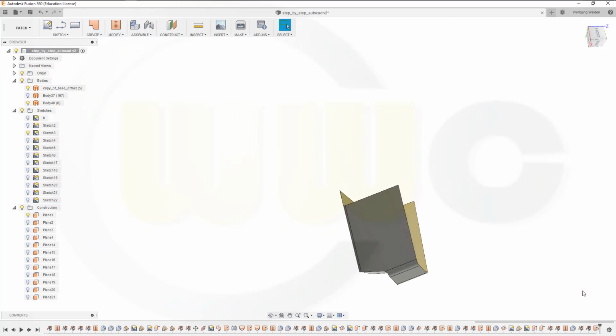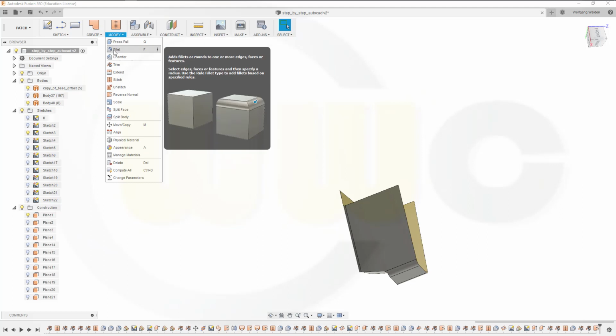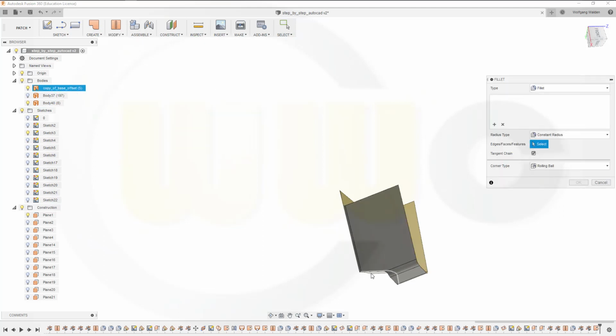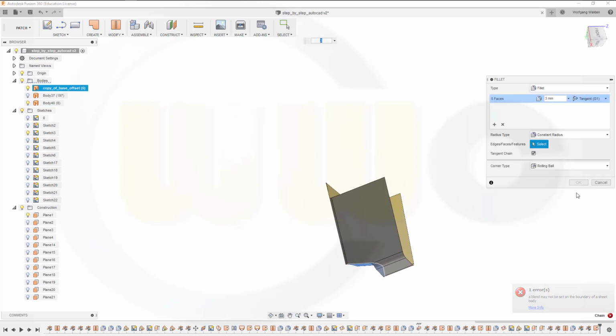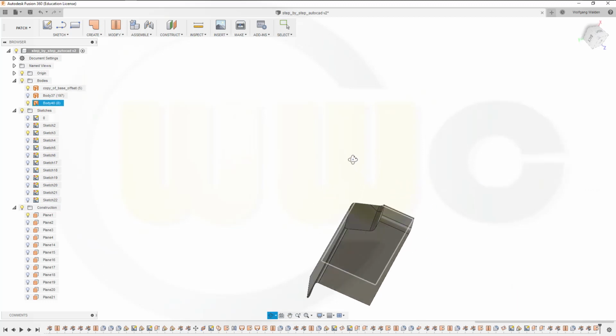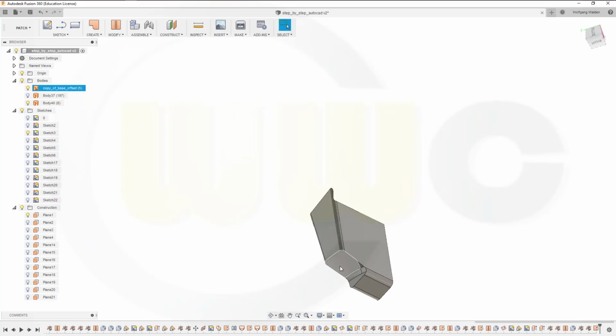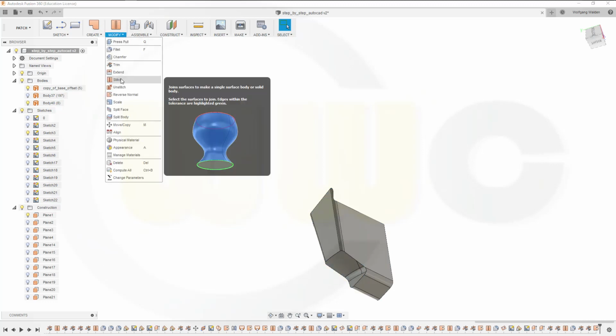Okay, now is it already stitched? No, that's a stitch, fillet. Okay, add another fillet, maybe 3 millimeters on that edge. No, not possible. Let's take a look. Oh, it's not stitched. Okay, that's the problem, so stitch it.